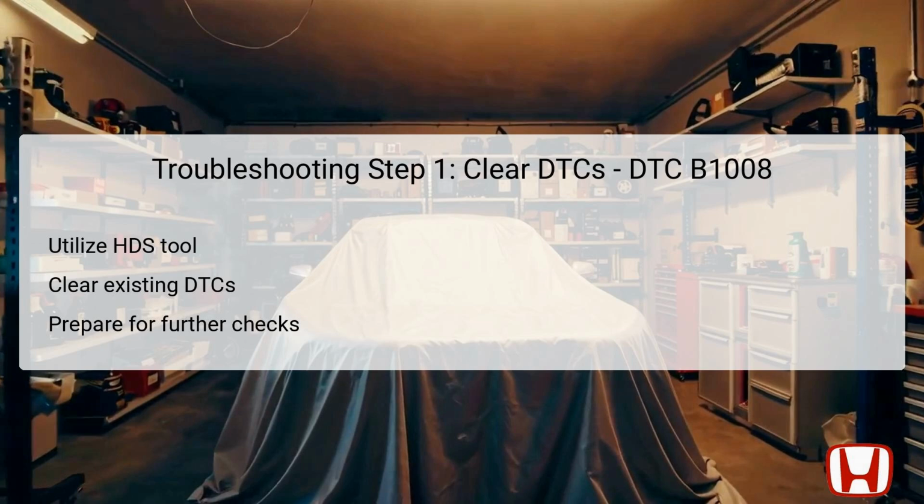This initial step helps in identifying intermittent issues that may not appear consistently. If the DTC clears and does not return, this often indicates a temporary problem rather than a permanent fault. After clearing the codes, it is crucial to follow the subsequent steps to ensure a comprehensive diagnosis.